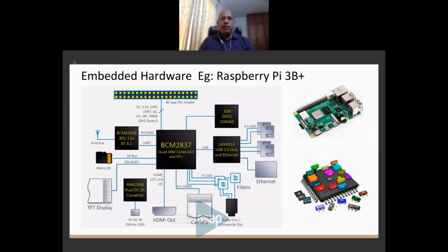System on chip is nothing but an integration of a CPU along with a lot of peripherals. So it is like the puzzles which you all play with. Semiconductor designers basically package multiple peripherals, like what you can see on the extreme right and bottom, and then they make SoCs. So SoCs get embedded on printed circuit boards like this, to make printed circuit assemblies, and then you get powerful platforms like Raspberry Pi.